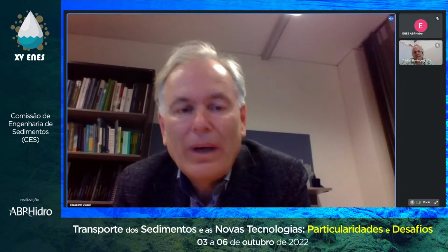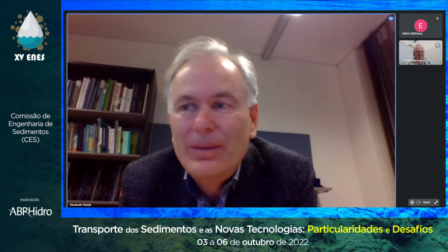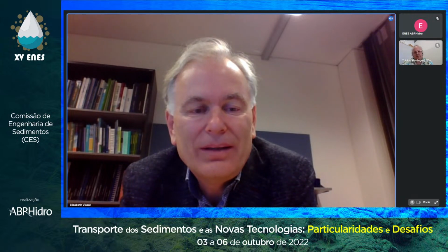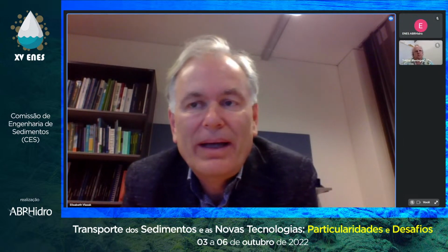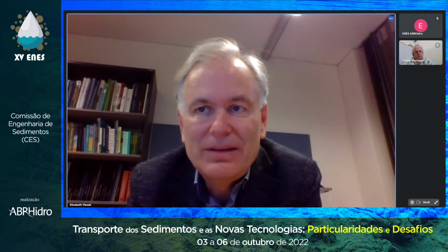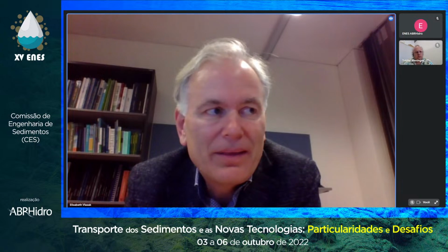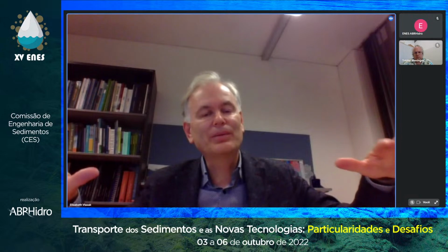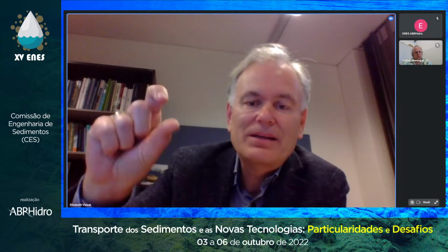Yeah, I think it's not one methodology, it's a combination, as you also say. What we use here is multi-beam echo sounding, so at the end you get really a 3D model. Sometimes we have 50-meter distance cross sections with single beam echo sounding, but I think the future is more the multi-beam, so we get really a 3D model. This is quite accurate, one way. We need somehow the surface of the sediments. And then we found out, as you say, where is the surface of the sediment? Even the echo sounder has some uncertainty.